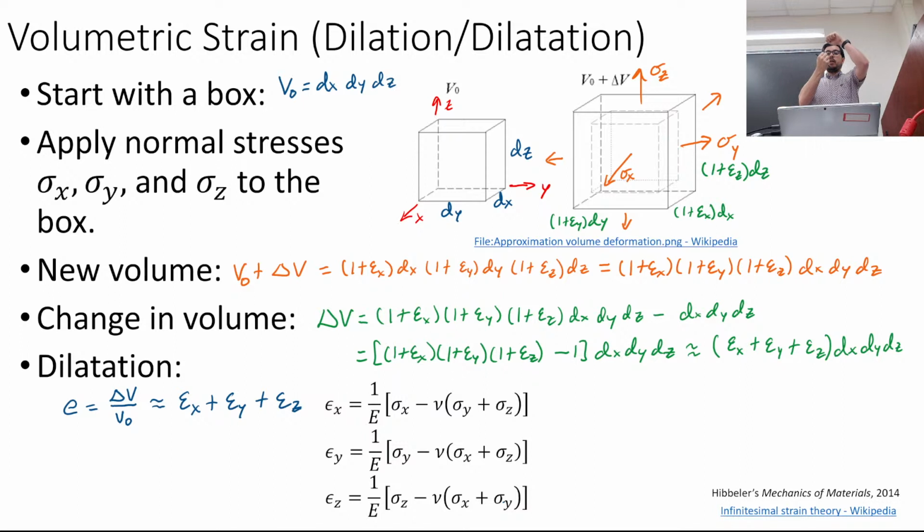But if I now have stresses in the orthogonal directions, and I'm pulling it in tension in those two other directions, the strain in that x direction actually goes down, because I'm pulling it apart in these other directions, so it's going to want to go this way. And that's true for the y and the z directions.